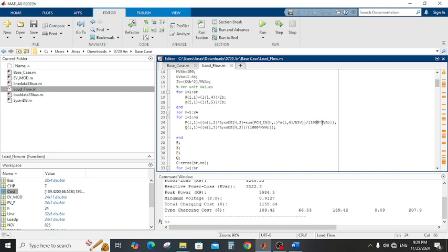And after that we divide by the base MVA, and the reactive power depends only on the nominal reactive power of the system multiplied by the profile of the system data bus and divided by the base. So this is the main thing that we change in each hour, the power and reactive power. And after that we make load flow to calculate the losses dependent on the real power and reactive power that we calculated on each hour.